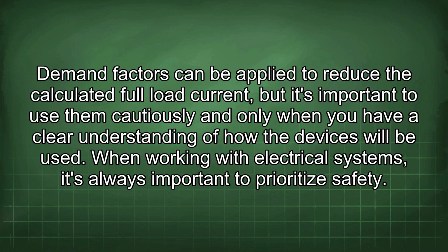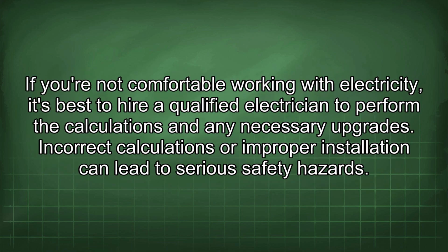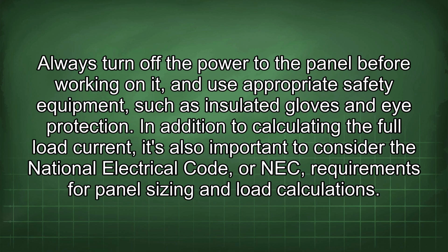When working with electrical systems, it's always important to prioritize safety. If you're not comfortable working with electricity, it's best to hire a qualified electrician to perform the calculations and any necessary upgrades. Incorrect calculations or improper installation can lead to serious safety hazards. Always turn off the power to the panel before working on it, and use appropriate safety equipment, such as insulated gloves and eye protection.